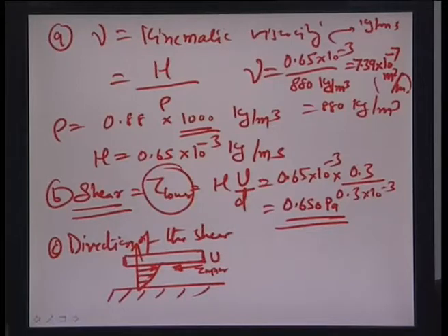Simultaneously, you are trying to deform the fluid element, so it is giving a pressure to this fluid in the other direction, more towards the movement direction here on the lower plate. It would have been better if this plate would have been able to carry this through along with it, but since it is not carrying it, the force that is being felt on this, due to this resisted layer at the junction, is actually towards the direction of motion of the upper plate.